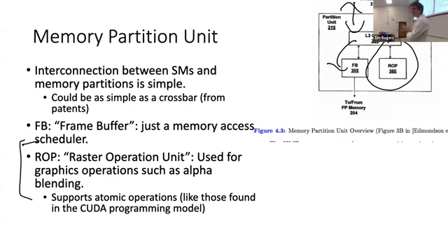This is the coherence problem that is a huge issue in CPUs. When you try to do read, modify, write in an L1, it's kind of a pain. That's what you did in 437 for those of you who took 437. I think you did load-link, store-conditional. You had to implement that. Imagine trying to do that in a GPU with all these threads trying to modify something at the same time. It would be disastrous.